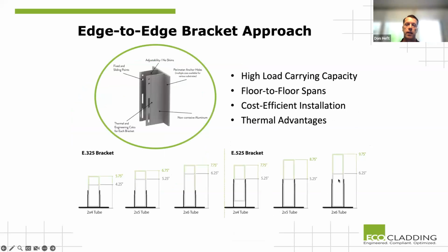We're basically taking something similar to a curtain wall anchor system going back to the wall, and it might be attaching to a slab edge, it might be attaching to some type of steel coming off the wall. This allows us to actually use tube systems, whereas the other systems we had mentioned are typically going to the wall at every stud or every other stud, and some vertical spacing of, let's say, 2 feet or 3 feet.